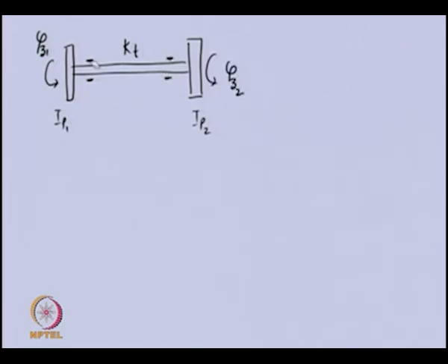So, these bearings are not providing any friction, and basically when this system is under torsional oscillation, the boundary conditions will be something like free boundary conditions, because there is no support which is restricting the motion of these two discs. So, free boundary conditions.